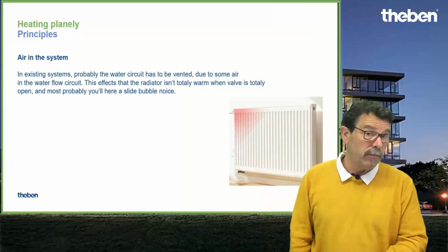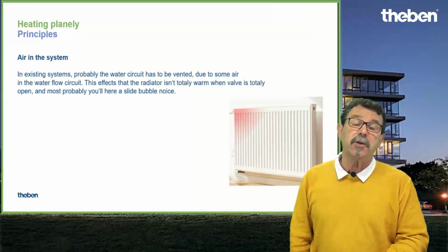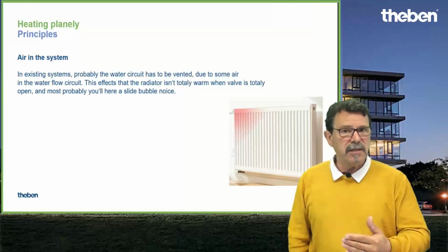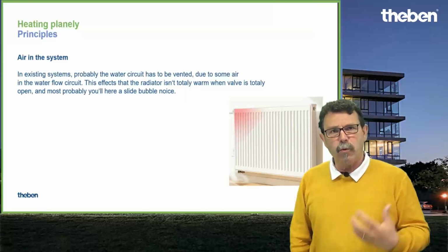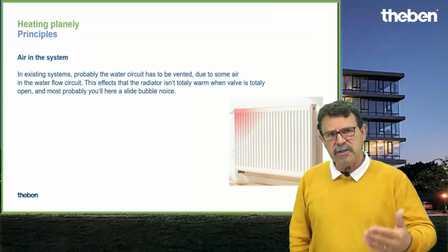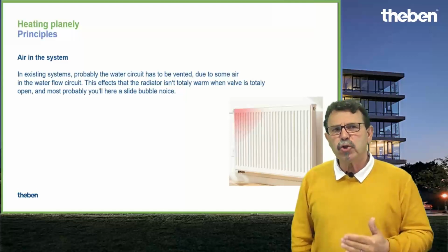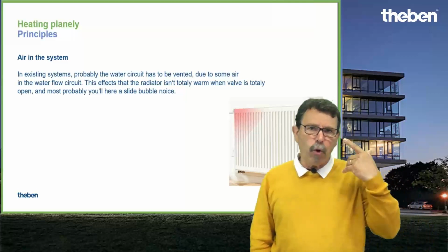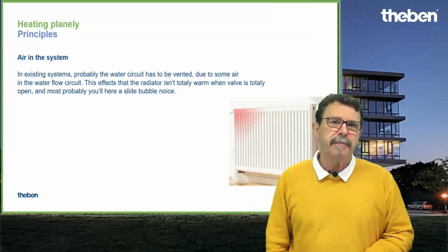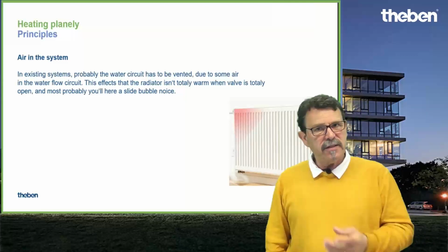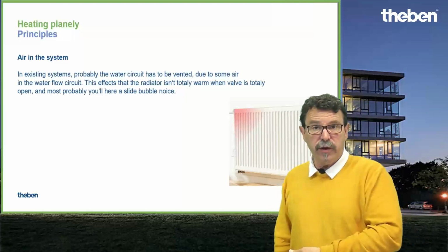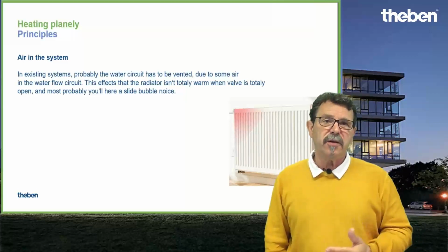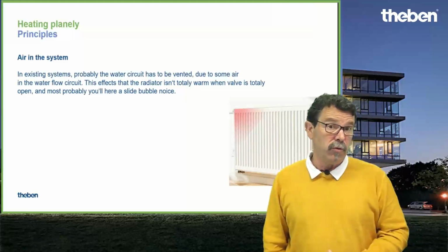Pretty simple. In older systems, or probably even in new systems, there could be air in the system. Basically, these tubes are filled with warm water, with liquid, and in this circuit there should not be any air, because then you have noises which sound like bubbles. And this means that such heating systems, could be underfloor heating, could be radiators as well, do not constantly give you the same warmth into a room.